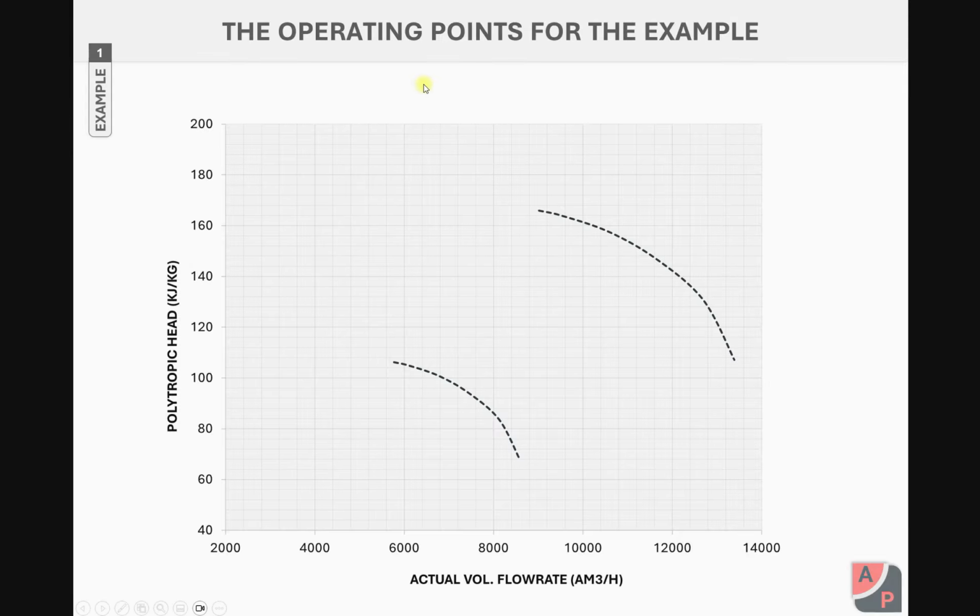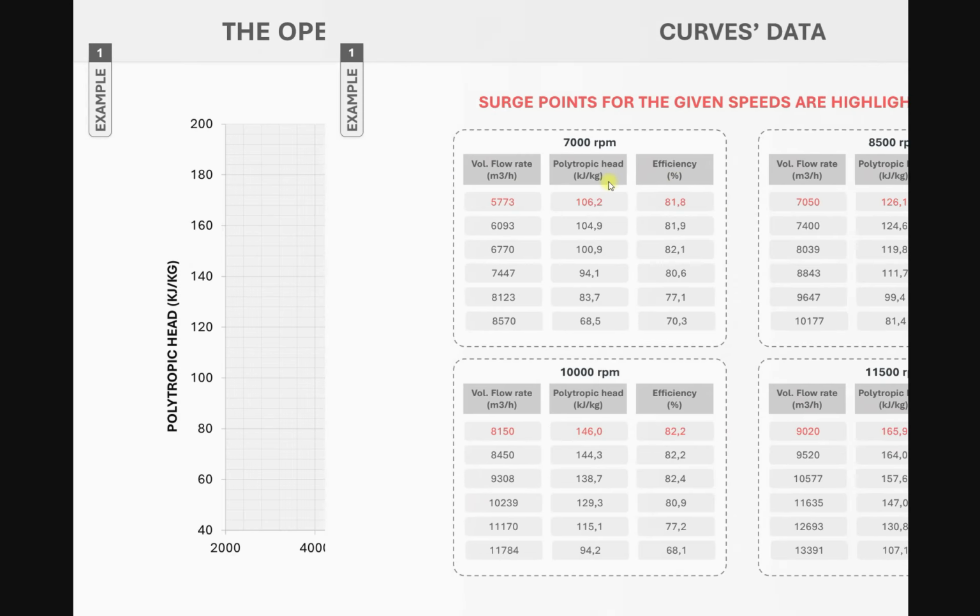You remember we had 6 cases in the previous sessions. If you want to map them based on our compressor curves, you can see clearly one of the cases is on the left side of the surge line and surge control line, so it requires some recycle flow. These 2 points also likely have slight recycle. These 3 points are okay.